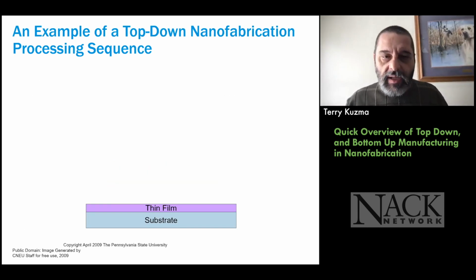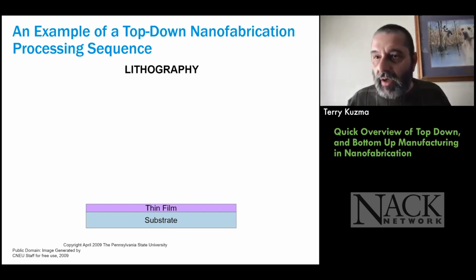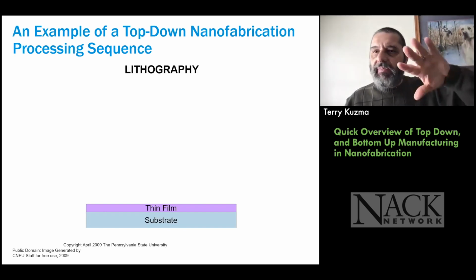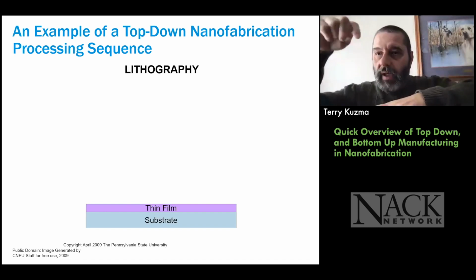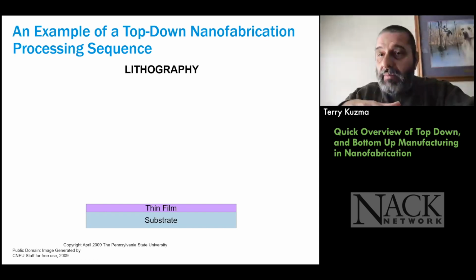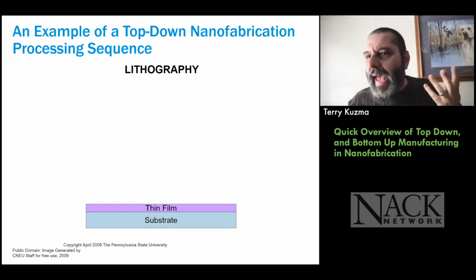And now what we did is we have my oxide on there, and I'm pushing the buttons and waiting for that to happen. Nothing happened. So now I'm going to do patterning, lithography. And lithography, like I said before, is like cutting your name out on a stencil, then being able to either spray acid down or deposit metal or something like that. So it's a patterning thing.